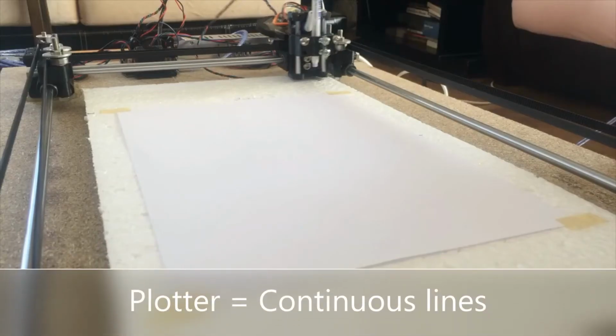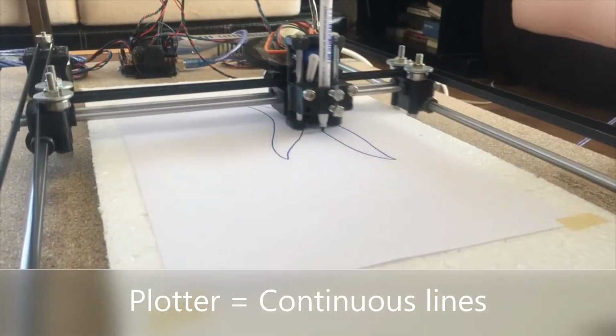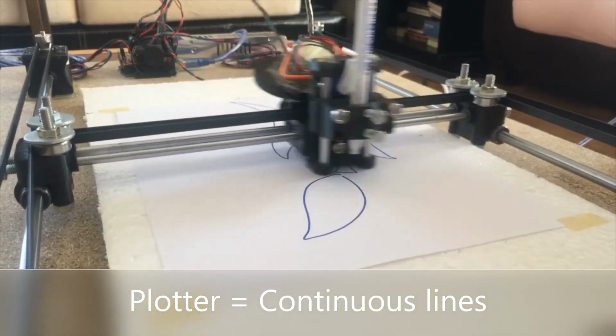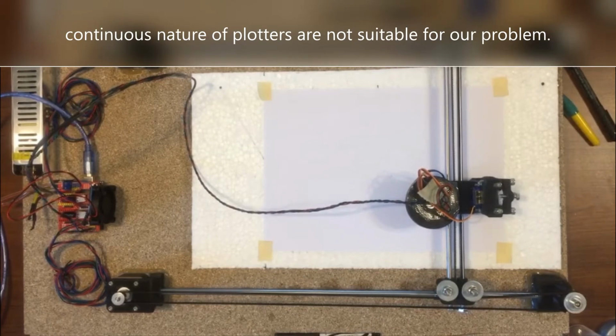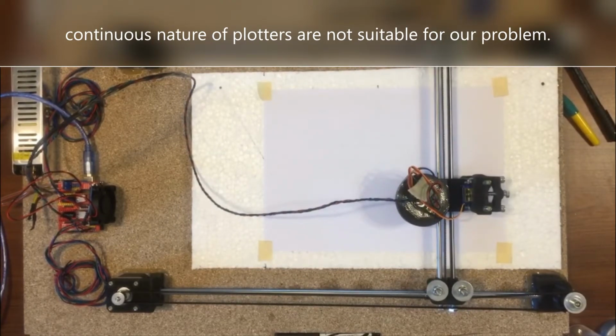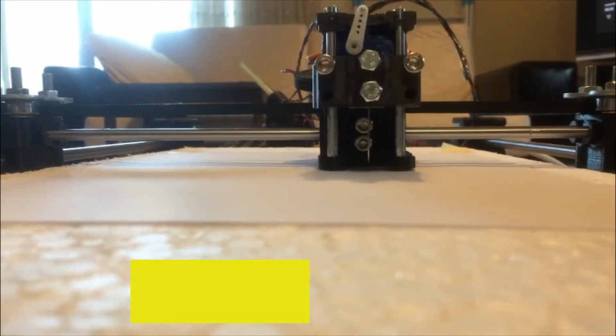The plotter should be able to follow continuous lines obtained from the image, but convert them to discrete intervals to place dots where needed. For this, we developed a method of conversion for dot placements and a custom-made needlehead for piercing the dots.